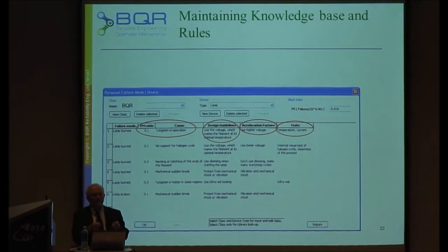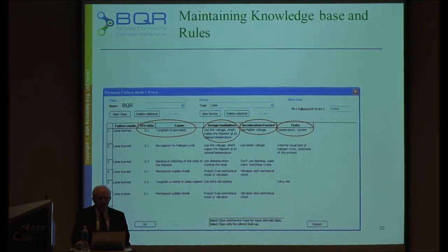When we did the analysis, we analyzed when it gets the power. Do you get it immediately, or at a slow rate? Once we looked at it, we saw that it goes in a ramp. We said, okay, designer, you need to build an automatic dimmer here so that the voltage goes slowly, or the rate should be slower. And this is what we, as reliability engineers, can contribute to the design: showing them the failures that can happen and how they can improve the design.